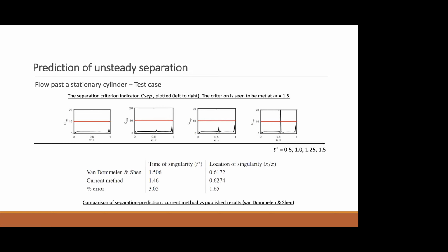So there is potential for some very nasty numerical singularities on the surface tangential velocity once you have these shed vortex sheets either at the separation point or beyond it. Do you think this vortex method, which so strongly relies on your accurate computation of the boundary layer, would still work now that you are in a separation region?